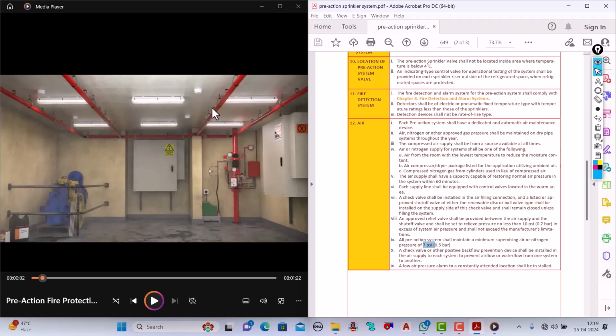If somewhere a sprinkler accidentally breaks, then the pressurized air will be released, and when it is less than 7 psi, the low pressure switch will send a notification to the fire alarm control panel, and the panel will activate the bell or sounder flasher, and it will notify the employee that somewhere pressure is low due to something happening in the system, right?